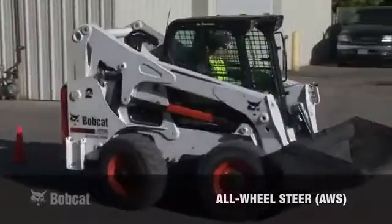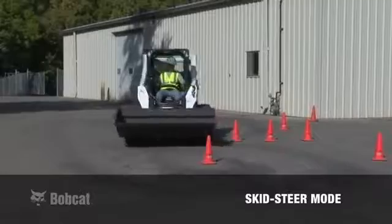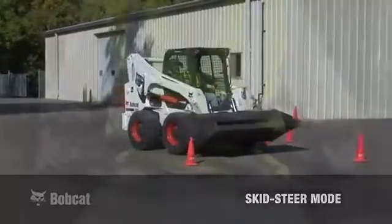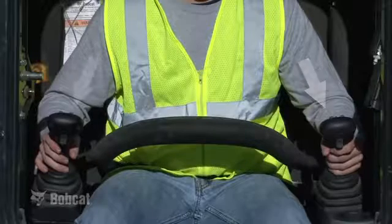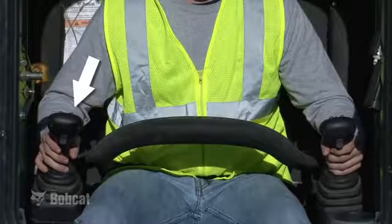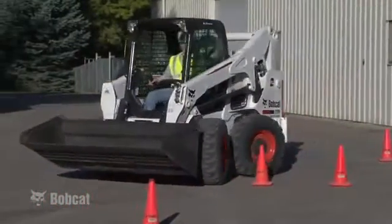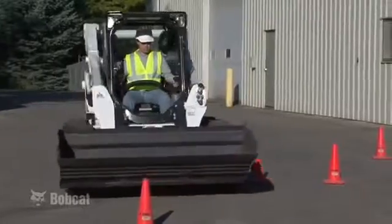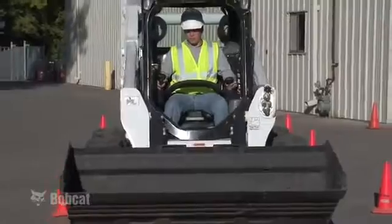The operator can select between two different steering modes, the all-wheel steer and the skid steer mode. Regardless of the steering mode selected, the left joystick controls drive and steering functions, while the right joystick controls lift and tilt functions. When in AWS mode, you get precise steering from the coordinated action of all four wheels. If high range speed is selected, only the front wheels provide steering.